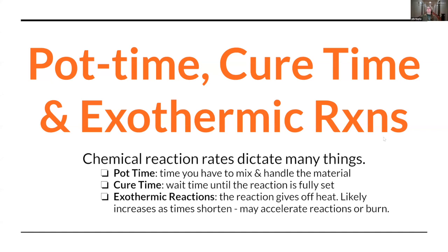So for your purposes, when you're starting out, your pot time or pot life, your cure time, and whether the stuff heats up as it cures are going to affect how it performs for you. And the rule of thumb is give yourself more time. You always want to get a material that's going to give you enough time to get everything done, because you don't want to be rushed. You don't want it to suddenly set when you're not ready for it, because that's when you waste materials, right?